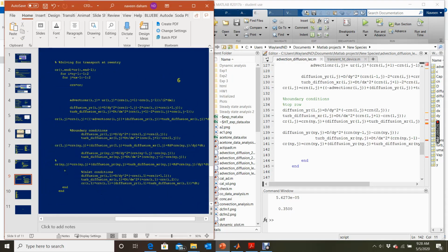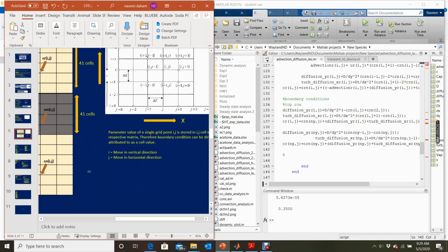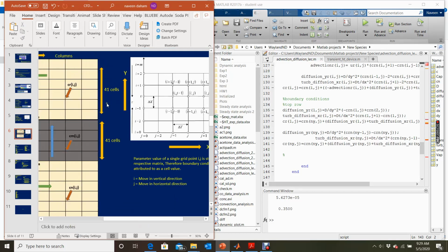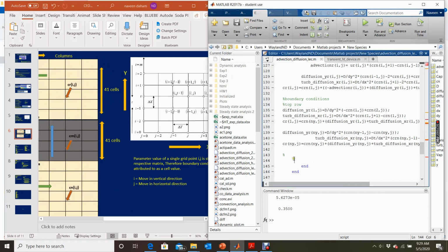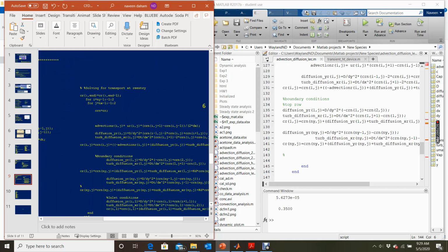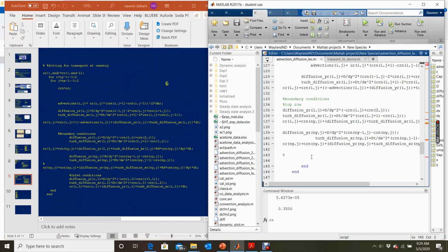Now again we are using a different method, because we don't have a specific concentration at the inlet of the exit channel. So what is the inlet of the exit channel? It is here. It is this surface, right? You know that at the inlet of the inlet channel we gave a concentration of 7.48, right? We don't know the concentration here. So what we're going to do is solve the diffusion equation freely for that surface. It will automatically generate its own concentration as time evolves.